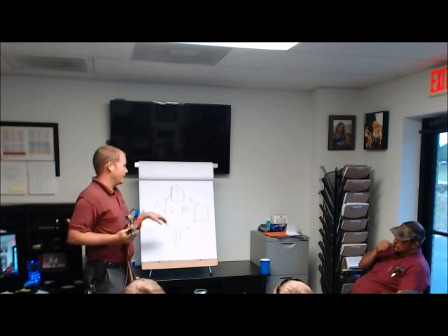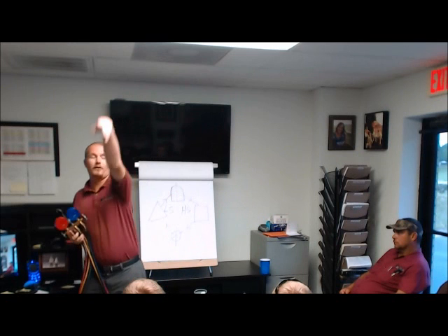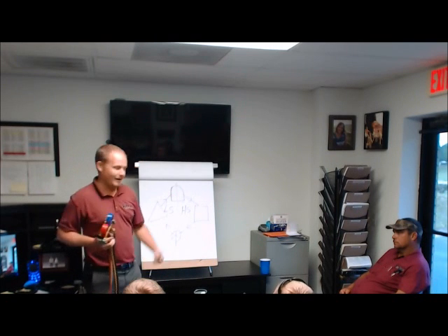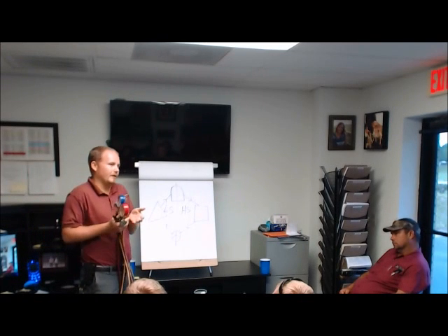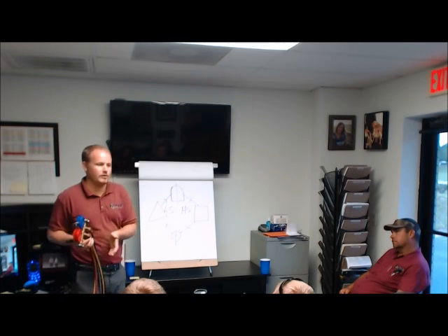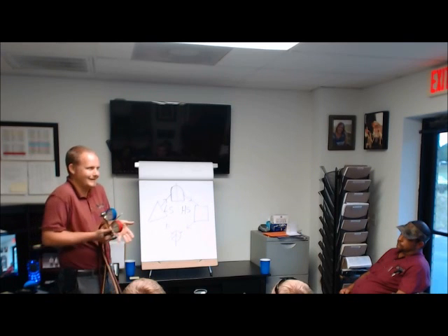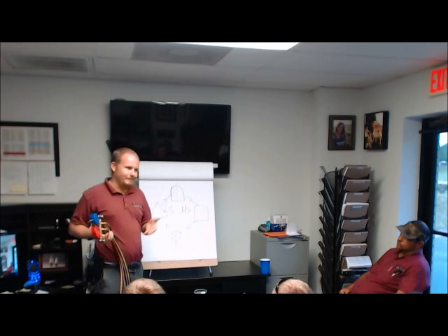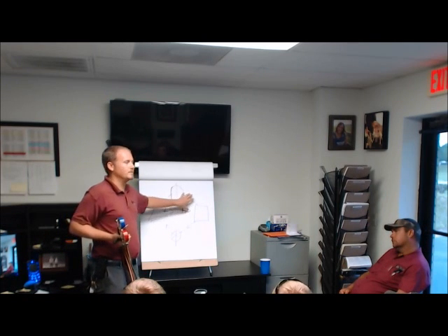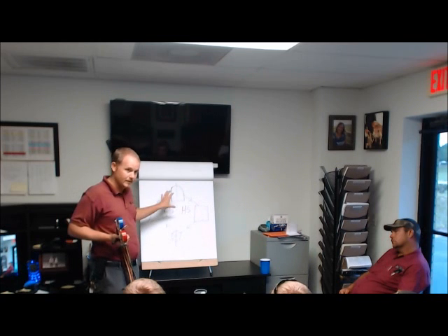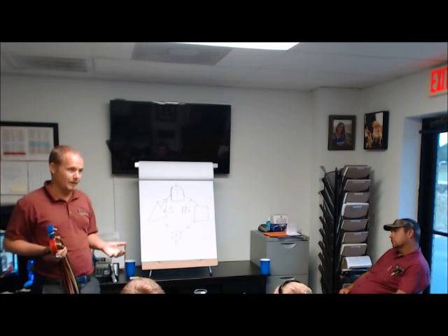What I used to always say in class is I could build an air conditioner. I could take a condenser, put it over there, I could take a compressor, put it on the other side of the building, an evaporator over here, expansion line, and a metering device over there, and just hook them all together and it would still work. We tend to think of air conditioning systems in terms of an air handler and a condenser, which are a standardized grouping that we use in a split system in residential applications. But that isn't how it has to be. That's just how they do it in production air conditioning. But thinking of an air conditioner in terms of its four components and its four lines and the different states of the refrigerant in the lines is much more accurate, and it will help you think much more clearly about what it is that you're accomplishing.